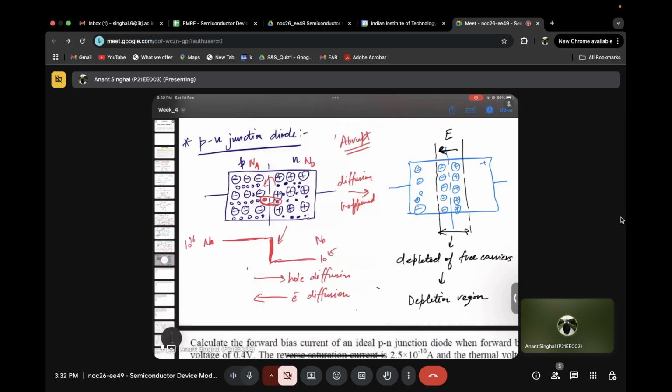Yeah, so one more thing that we just saw. So this was a PN junction, and we just made a band diagram if you remember, and it was looking something like this, and then this, and then this, and then this. So the electric field direction, you can just directly judge from the band diagram that it is always up the hill. That means wherever the band diagram is going upwards is the electric field direction. For this case, it is from right to the left of the screen. I hope it is clear to everyone.